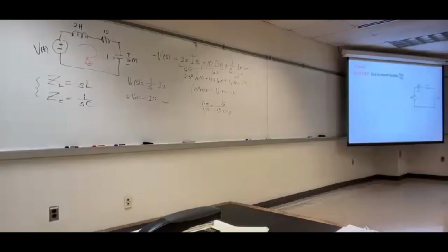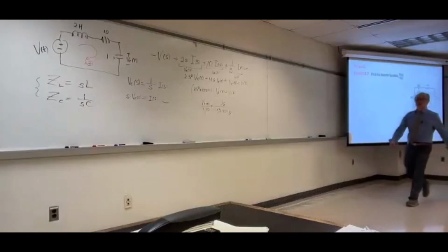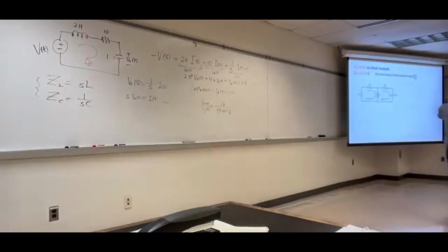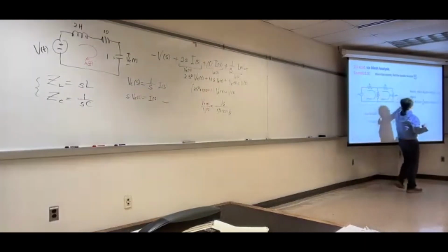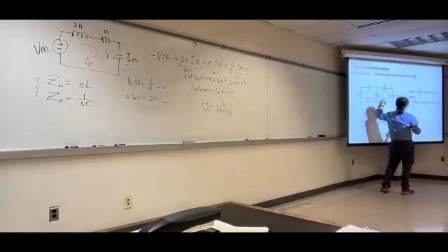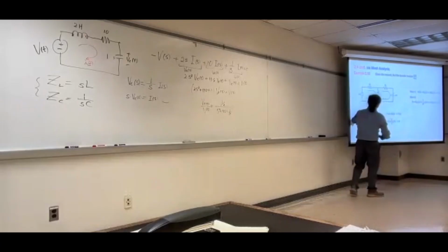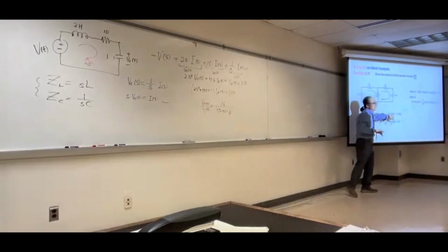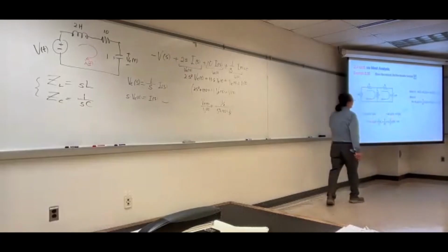That's too easy, right? A one-loop circuit is too easy. For the exam and the quiz, you're not going to see one loop. It's a minimum of 2 loops, something like this. Now we need to use mesh analysis and nodal analysis. Basically, we want one equation using the mesh current here, a second equation from the mesh current here, and then we're going to organize in terms of I1 and I2, and then use Cramer's rule.